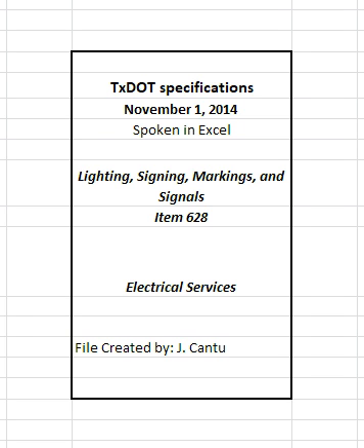For the installation of electrical services, use new materials that meet the requirements of the NEC, UL, CSA, and NEMA, and are in accordance with DMS 11080, Electrical Services. Provide pre-qualified electrical services from the department's MPL. When required by the engineer, notify the department in writing of selected materials from the MPL intended for use on each project.